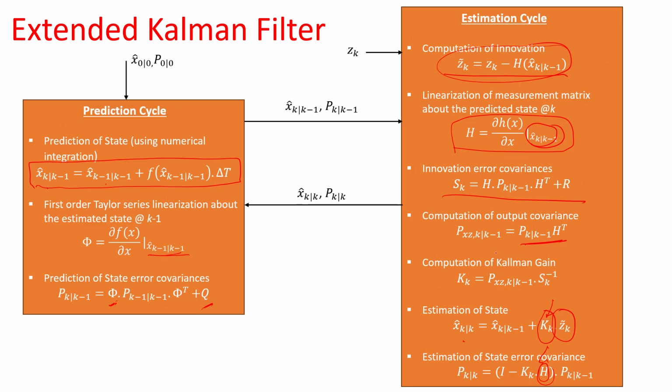You should remember that I have not used this linearization here, not even in the predicted state calculation. When I am calculating the residual, you see I have used the nonlinear function h of x k given k minus 1. I have not used the linearized value in computing my predicted measurement.